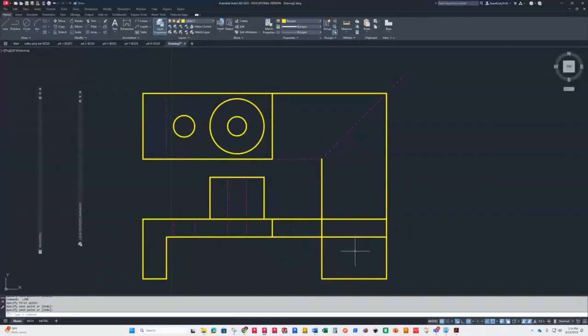And see, the reason that I want to draw this view is so that I would see both of these edges. Because from this side, this edge has to come through here, which makes it hidden. So this has one less hidden line than the left side would. So that's why we're drawing this view. All right, so I don't need those. Don't need those. There we go.